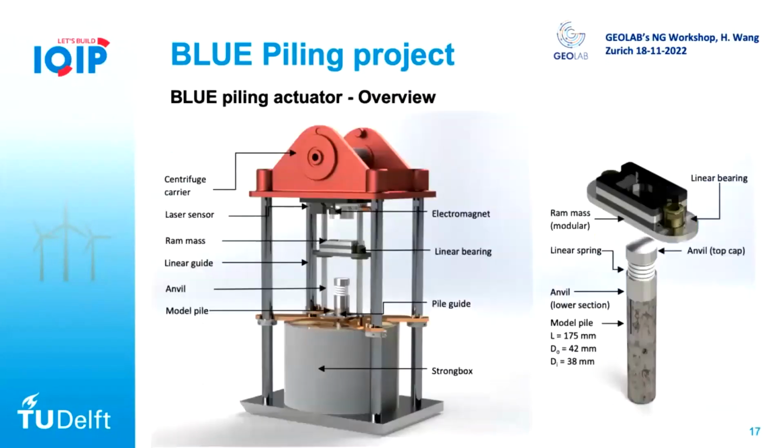And even further, we also developed a hammer system specifically called the Blue Piling actuator. Basically, in between, instead of a buffer, we also put in a linear spring to simulate even more, to eliminate more bouncing back, to make sure we have more interaction and more energy transferred to the pile.